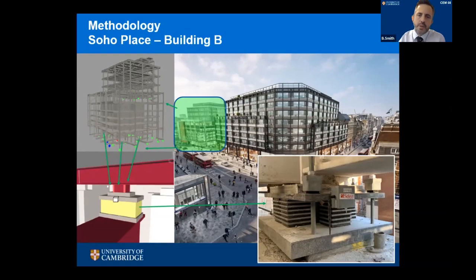As the structure was built, the displacement of the bearings was measured, and the load from each column was calculated using the stiffness of the bearings. I compared the measured loads with the predictions made by the structural engineer who were on this project. The total load measured was within 9% of the predicted, which I think was a good result.